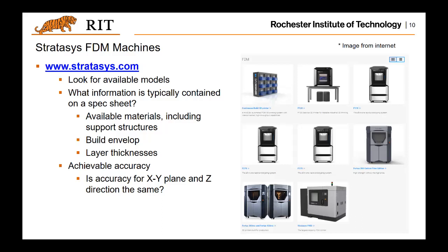Well, we have yes and no, and the answer is no. If you take a look at the process, we have more continuous motion in XY plane, but a discrete motion in the Z direction. And also because of the layer by layer processing pattern, it turns out there will be a weakness along the Z direction as well as in the part accuracy. So it has a higher accuracy in the XY plane versus the one in the Z direction.